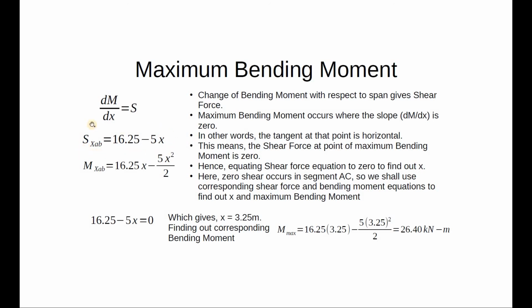The shear force expression in that segment is given by Sx_AB equals 16.25 minus 5x. Equating this expression to 0 and finding out x, we get x equals 3.25.